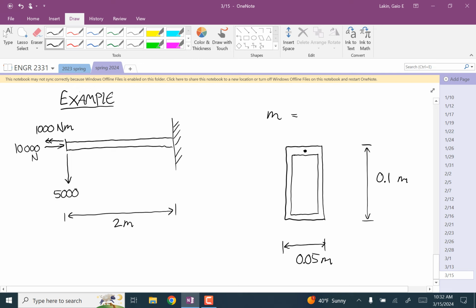And let's say the thickness looks like it's different everywhere, but let's say it's the same everywhere, 5 millimeters. So we know that with this approximation, using a thin-walled tube for the torque, we could be off by 5% or whatever, but we're going to accept that. And now let's figure out what the mass is.